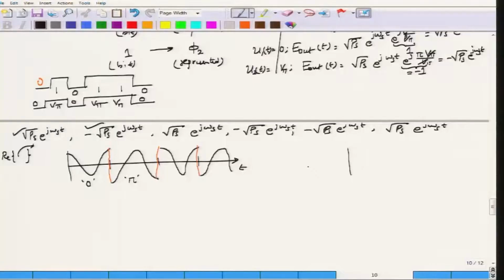Of course, we will revisit all these in much more detail when we take up higher order modulation formats. Before leaving the subject of BPSK, let me introduce you to one figure which we normally think of when we say BPSK, or this is how we represent BPSK. This figure represents what is called the in phase and quadrature components. It is a plane in which the x axis is the in phase component and the y axis is the quadrature component.